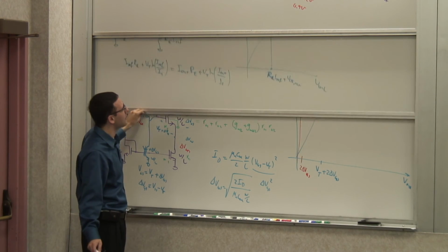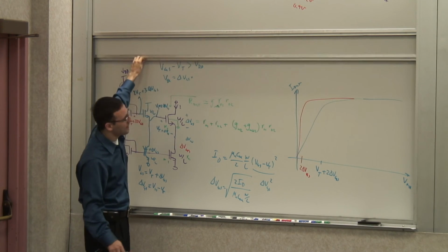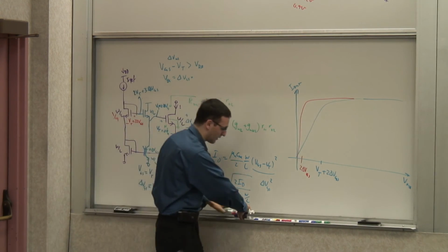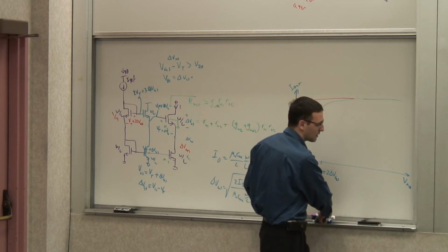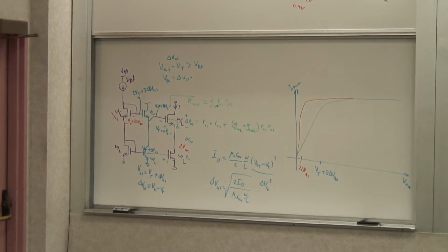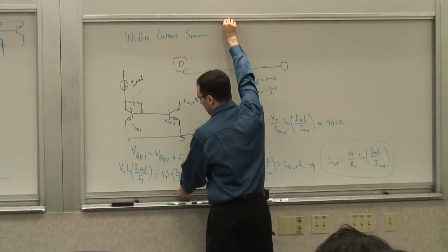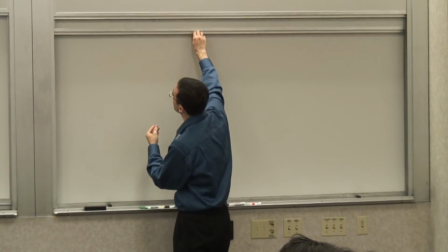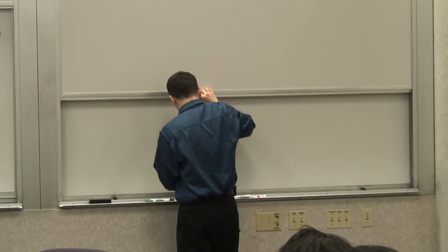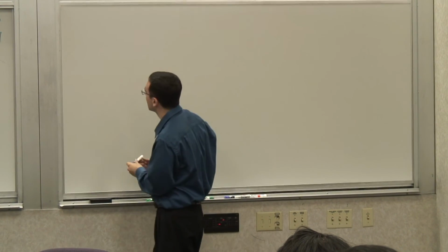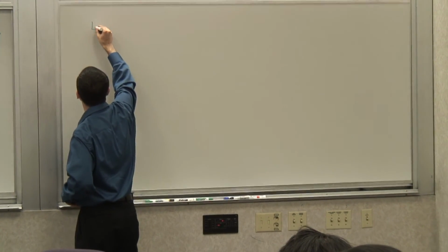Now, we've spent a lot of time on these MOSFET current sources, and I'll show you one example of PFET. But we can do everything that we did here in PFET as well. So if you want to use a Cascode current source, you can use it in PFET. And if you were to make a Cascode current source in PFET, it would look like this.